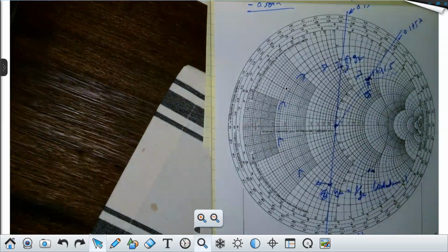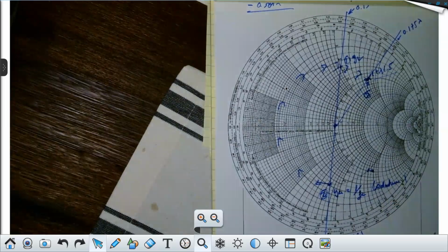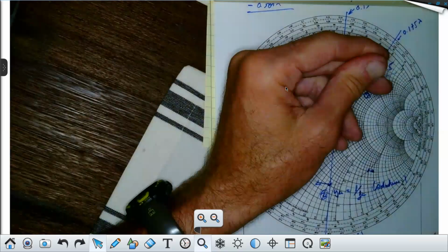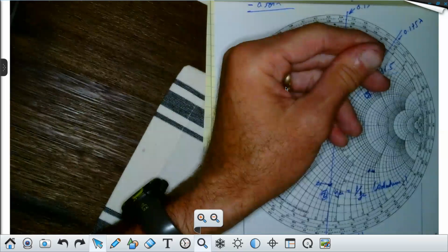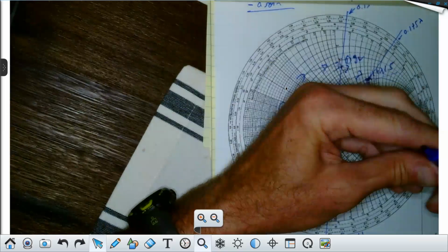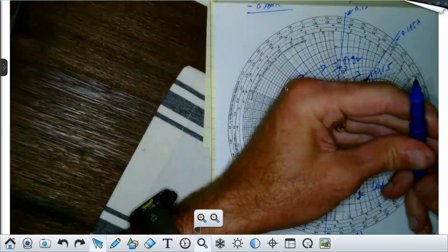I'm going to give you some homework. This is just impedance matching with elements. They have to solder in small little inductors and capacitors to do impedance matching. It can be tedious, but it's effective. On Wednesday, I'm going to go through impedance matching using transmission lines, where we either put a short or an open circuit at the end of the transmission line, and we replace the elements that were either in series or parallel with actual pieces of transmission line, finite lengths. This is done all the time. It's called stub tuning. You can read about the section in the book.